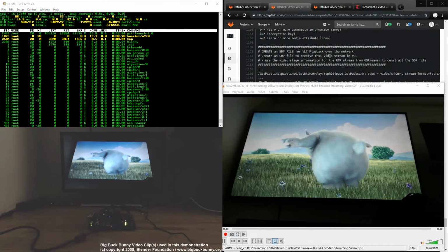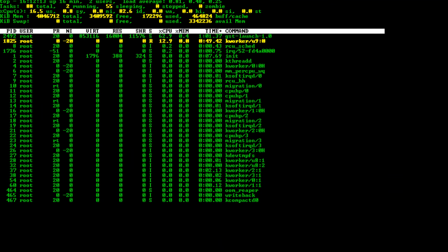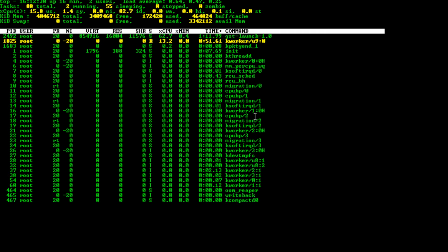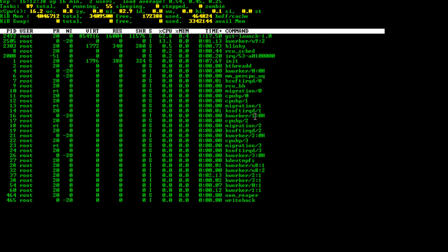We're still doing streaming over the network and playback locally. So I'm going to highlight here in Tera Term this top entry, gst-launch. That's the GStreamer pipeline's involvement, and it's about 62 to 64% of a single Cortex-A core being utilized to handle all the processing. So that includes buffering the data, sending it through the video convert element, which is a software piece. In an actual end application, you would probably want to implement that in hardware using a mixer or something in the PL to do your data format conversion before going in the encoder, so software doesn't have to actually touch that piece.